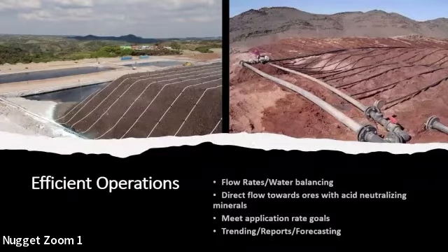So what we're seeing with the argillic ores is that maybe under 2, maybe 3 lift height conditions, it should be sufficiently permeable. And I mentioned this one blend sample that performed marginally well, so that indicated there is potential to blend this ore and still be able to have sufficient permeability under a couple lift conditions, 2 to 3 lifts.